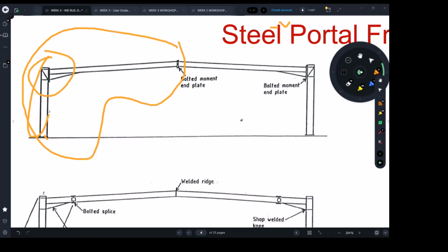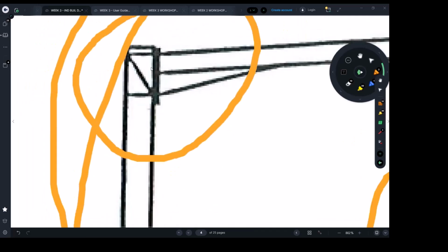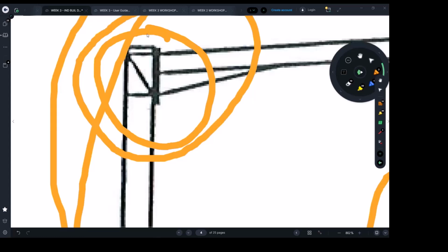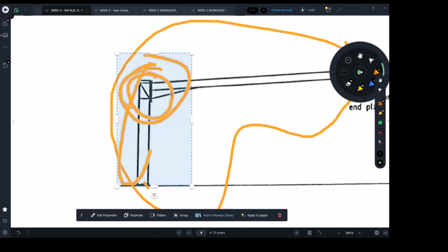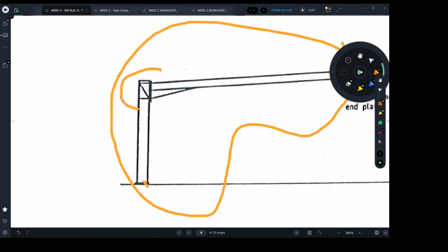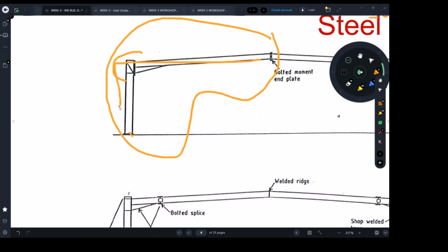This is again what we said about this. This is an expensive rigid joint, consisting of a lot of welding, bolting and stiffening. So as quality control, it's better to do it in the factory and get it craned. Doing this on site, where you need scaffolding and all that, you may miss the quality. So it's a good idea to make this joint in the factory, get it trucked and build the frame. So the option here is that you have to build all this, and it's still too long.